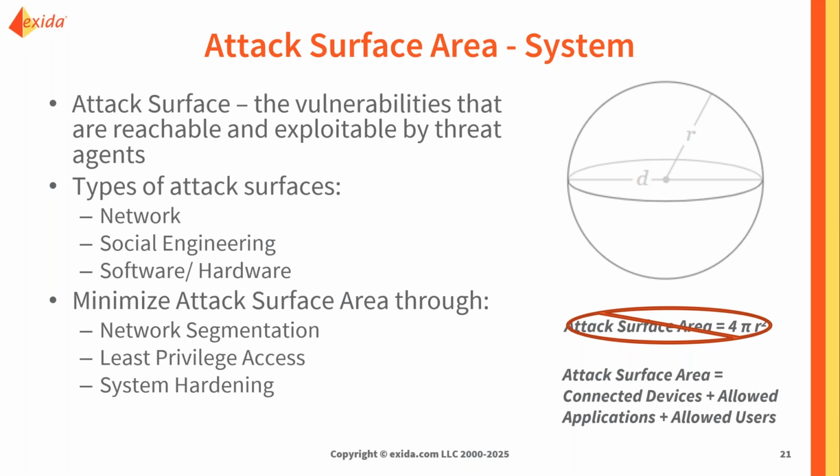If we look at our engineering or operator workstations in the industrial environment, there's an extremely limited amount of software that should be installed on those computers. Yet time and time again, when we go to sites and we evaluate and gather what's there, we're seeing internet browsers, we're seeing user-to-user messages, games, lots of bloatware, so things that just don't need to be there, and provide more of a foothold that attackers could use to find exploits and compromise the system.